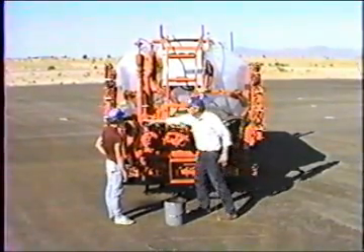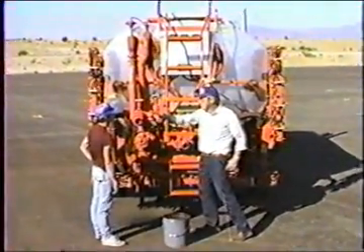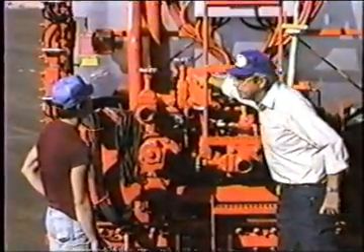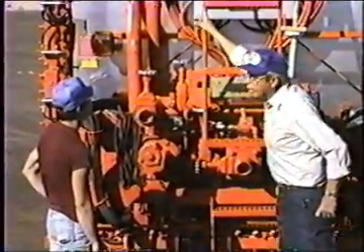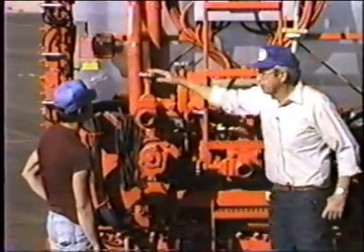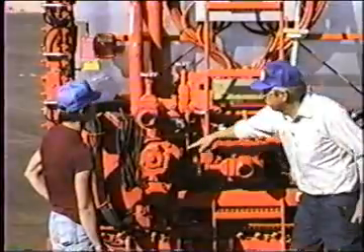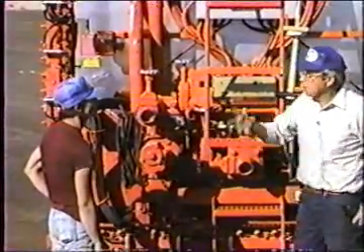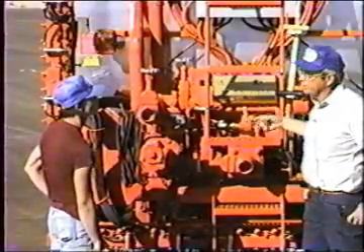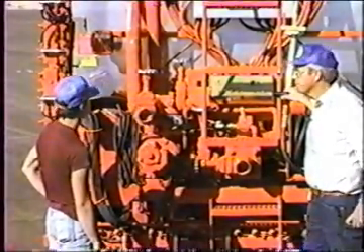Okay, we're going to put a hose on here and hook it to our tank. This is the only place we want it to go, so we'd be sure the bar valve is closed, and be sure that tank circulated valve is closed, be sure the handgun valve is closed. Open this, pumping forward since we're going in the bottom and out the top, pump our material off into that tank. When we get done, we're going to clean the pump and we're all done, close all the valves.